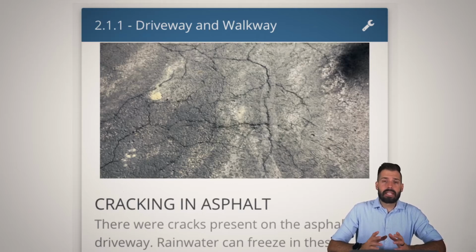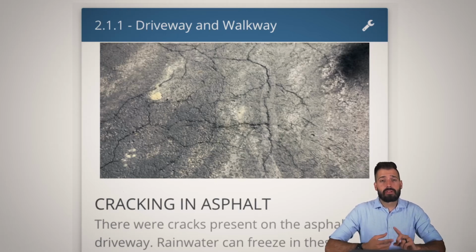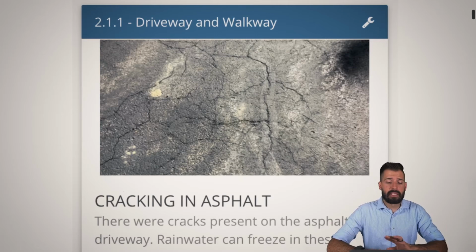Now, sometimes if the driveway has cracks that are too big, then we actually need to seal it in a different way, not just putting like a roll-on or paint-on kind of sealant. What we actually need to do is go in and patch holes, or fill in sections with either tar or an asphalt repair kit or whatever. So just keep an eye on how big those cracks are, but they're extremely common and definitely expected.